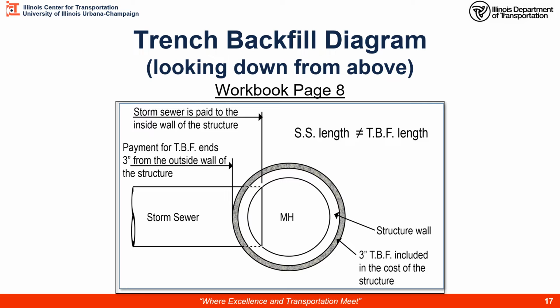touches the edge of the manhole. So that will be your pay length for pipe, comes inside all the way into the manhole. However, for trench backfill and the aggregate portion, you may measure to the manhole, but then you subtract off 3 inches to account for what's already been included in the cost of that structure. This is on Workbook page 8 also.